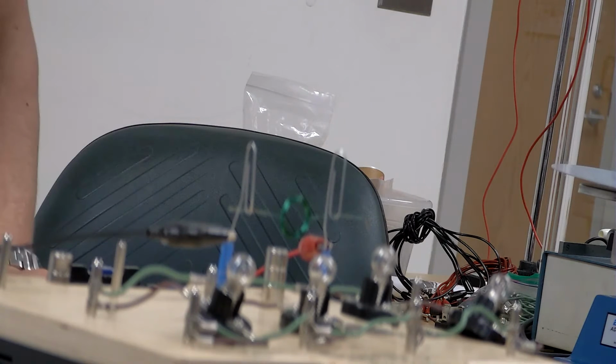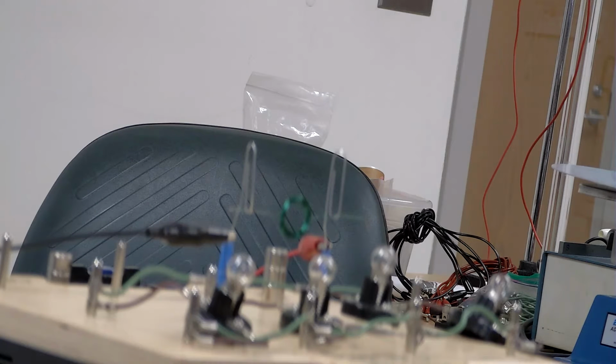I got a loop of wire, and I just looped it around a bunch of times, because you might think about this: if I put a bunch of square loops of wire, each wire that comes down here feels the same magnetic force. So I get more overall force with the more loops of wire I have, right? Each wire that's coming down on this side is going to feel that same force because it's going to carry the same current. And so to get more force on a loop of wire, all I do is add more loops, and I get more force without doing anything else.